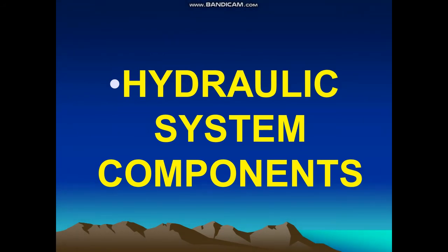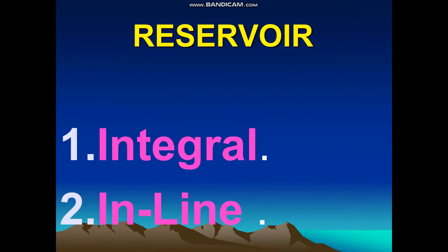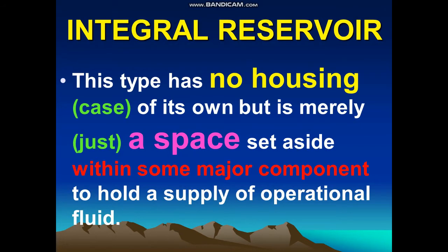Today we will talk about the hydraulic system components and we will start with the reservoir. We have the integral reservoir or the inline reservoir. The integral reservoir has no housing or case of its own but is merely a space set aside within some major component to hold a supply of operational fluid.